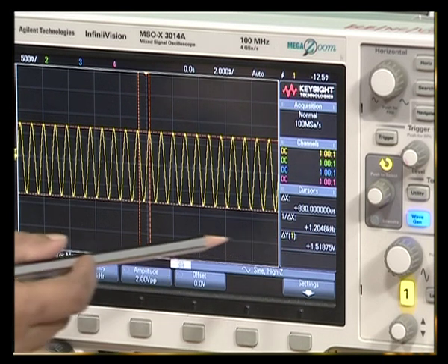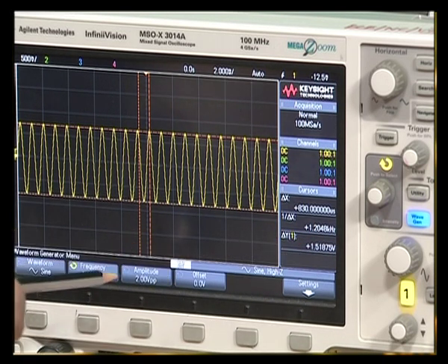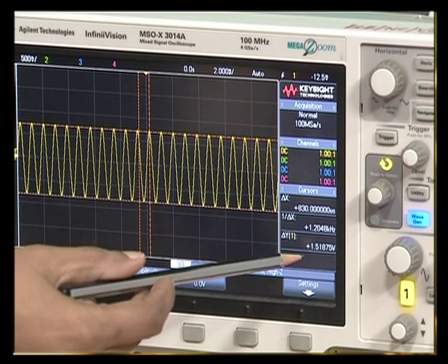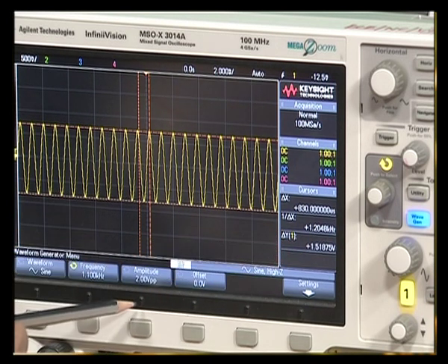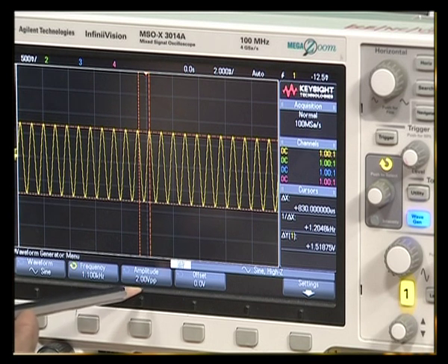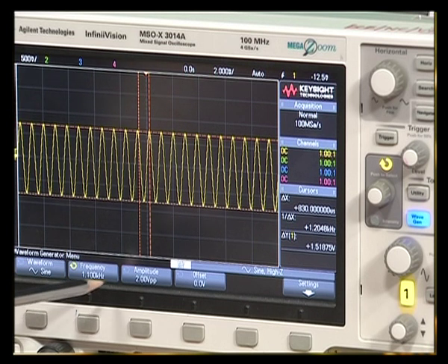When you find the gain here, that is the output voltage divided by the input voltage, the gain that you get here is minus 2.5 dB. At the other extreme, 11 kilohertz, a decade apart, the output voltage peak to peak that we got was 26 millivolts, and the gain there is minus 37 dB. Therefore, the difference is minus 35 dB.